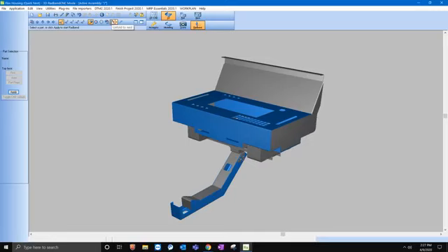I'm not sure how you guys are doing your bending now, but I just thought it would be good to share what you can do with offline bending. And you can do automatic tooling once again, automatic sequencing, and you can actually do batch bend as well. We have batch bending, so you could take all the 3D files, drag them into a folder, hit start, and you could process all your 3D files that you need for bending. I've got several customers who do that now.